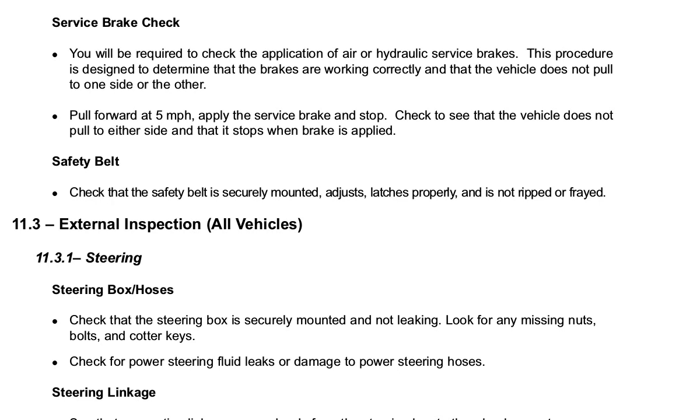Pull forward at 5 miles per hour, apply the service brake, and stop. Check to see that the vehicle does not pull to either side and that it stops when the brake is applied. Safety belt. Check that the safety belt is securely mounted, adjusts, latches properly, and is not ripped or frayed.